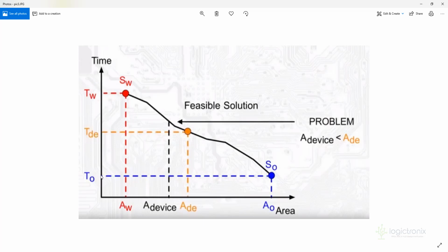It takes less time to calculate the hash, that means very high hash rate. This is low area, and this is very high area. So this is our best performance, best throughput, and this is the worst in terms of performance, with the worst throughput, but it also occupies less area. So these are the two extremes: the basic iterative architecture and the fully unrolled architecture.